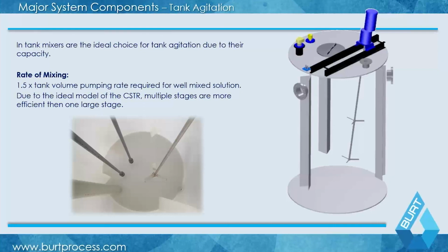That being said, recirculation pumps do have their benefits in these systems. We'll talk about that a little bit later in the broadcast. But that has more to do with the reagent injection, allowing that to actually be pressurized into the actual pH neutralization mixing, as opposed to directly being involved as a primary agitation source.